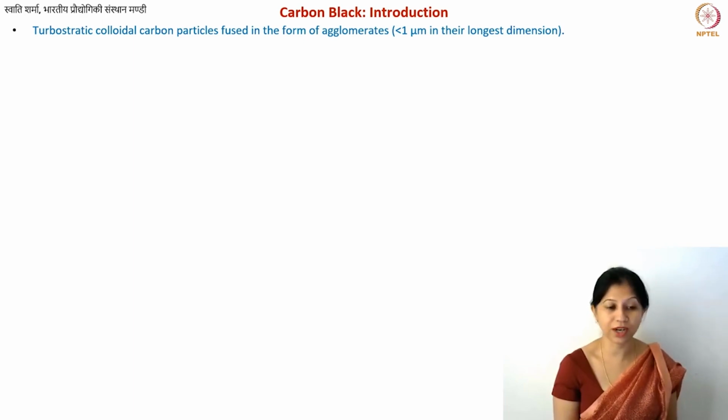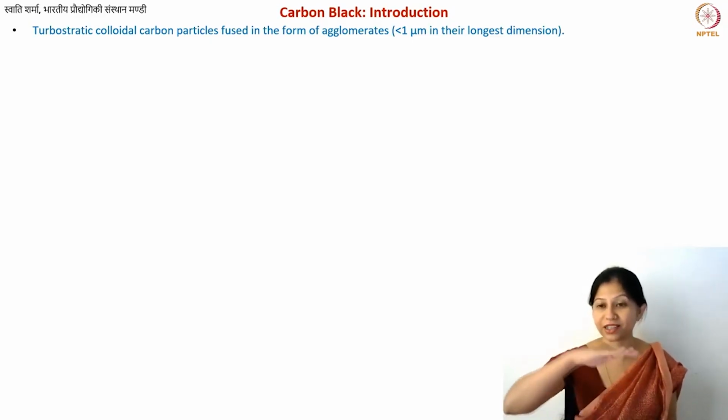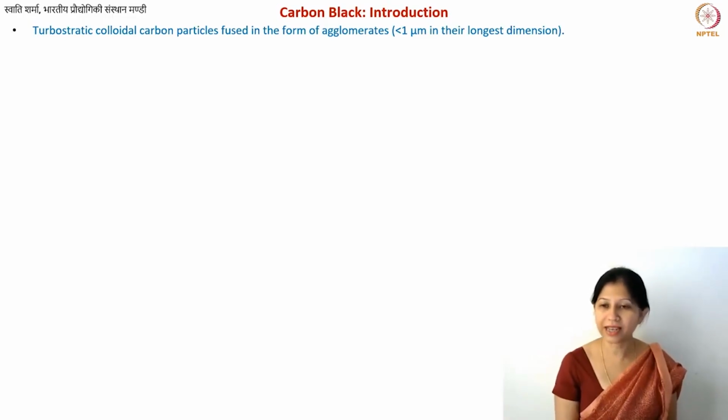Turbostratic is basically nothing but if you have these graphene-like sheets in any carbon material, and they are randomly rotated on top of each other rather than in the ABABA fashion, then you call it a turbostratic material. Often the materials that have strong curvature, curved carbon structures, tend to be turbostratic, because it's difficult for them to have these flat geometries and ABABA, graphite-like crystalline order. This is also a material with short range order.